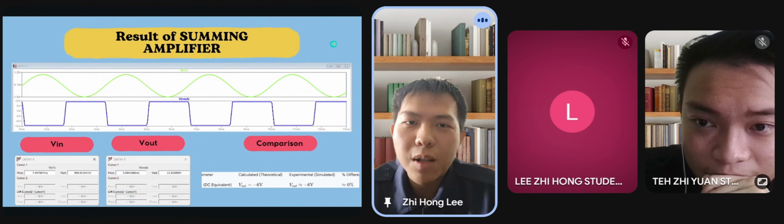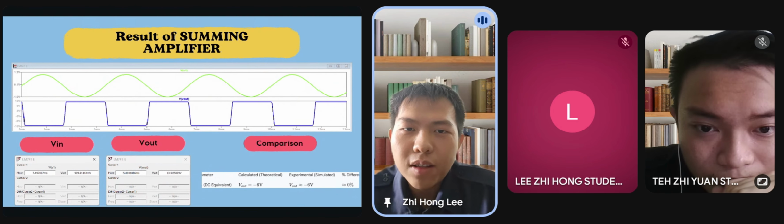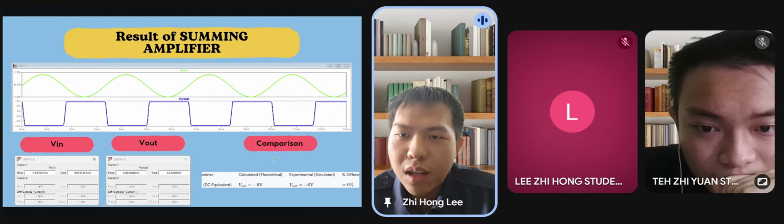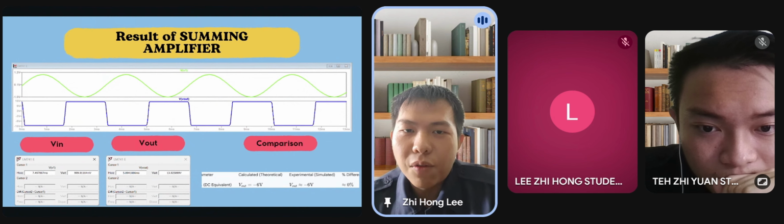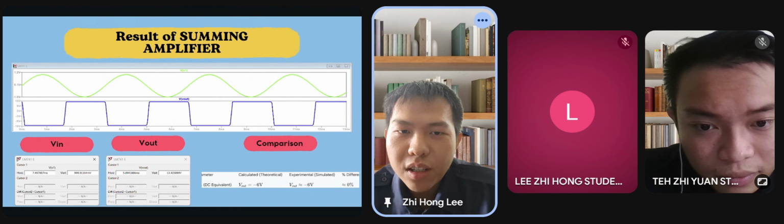Now I will explain the result of the summing amplifier. Our final circuit is the summing amplifier, and we calculated a weighted sum output of negative 6 volts peak, which the simulation closely verified. This confirms the core principle of weighted algebraic summation.